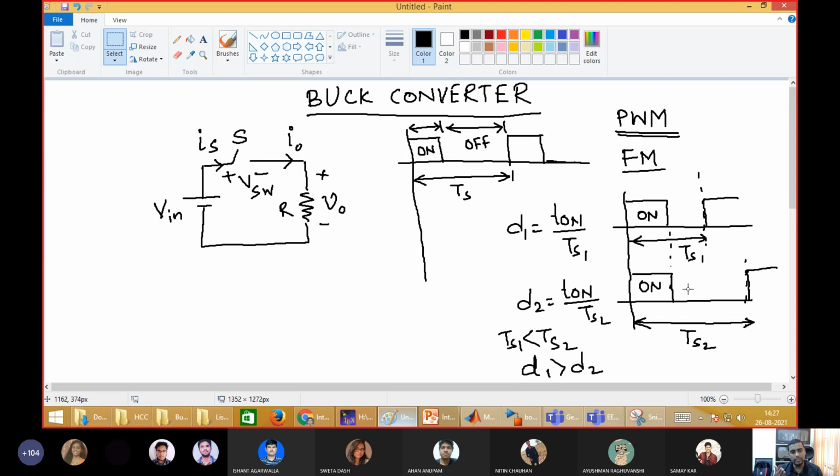But if we change the switching frequency, the switching loss occurring in that device will change. So the heat dissipated through that device will change, and whatever heat sink you designed will not be adequate to dissipate the heat generated by the switching loss. So these are the two main reasons we try to keep the switching frequency constant, and that is possible only without frequency modulation.